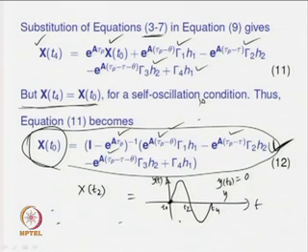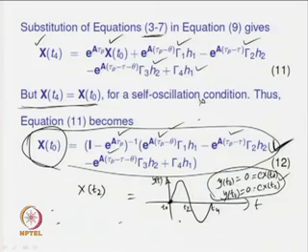Similarly, at time t equal to t2, the output y(t2) is 0. So, when you substitute, C x(t0) is equal to y(t0), which is 0. Similarly, C x(t2) is equal to y(t2), which is equal to 0. Then we will get further simplified expressions for equation 12 and the other one. So, keep in mind this can conveniently be used to find simpler analytical expressions, or nonlinear expressions, which can subsequently be solved to estimate the unknowns associated with the second order plus dead time system.